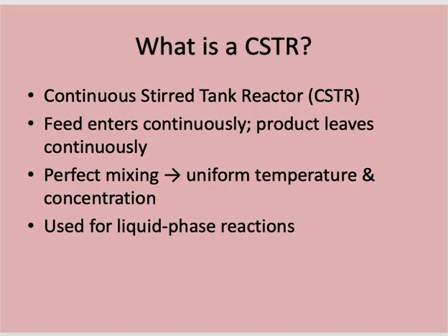First of all, CSTR. This is continuous stirred tank reactor, which means that you will face a tank, and inside this tank there is an agitator, okay, and there is an inlet and an outlet from this tank. Is it all? Not like this. You will see through the lecture that you have some kind of feed enter continuously and the product leave continuously, okay, or you can find the process happen batch wise.